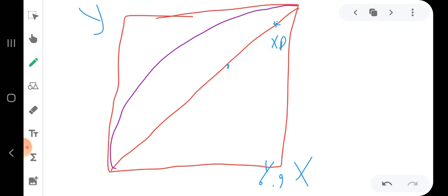Then you need to determine where your ZF1 and ZF2 are. For example, if it is here, say 0.7, this will be ZF1, and if ZF2 is 0.4, it will be here, ZF2. Then you need to determine XW. For example, if it is 0.1, it will be somewhere here. So you need to determine XD, XW, and not only one ZF, you have two, ZF1 and ZF2. Now the second step is to draw the Q line.